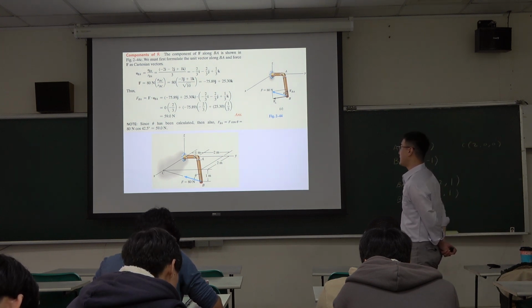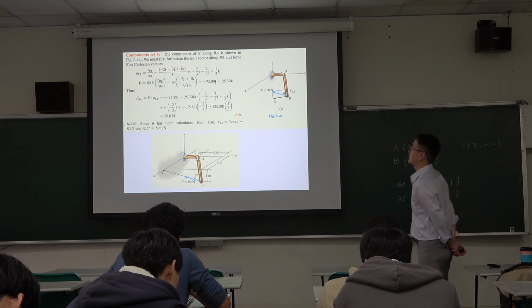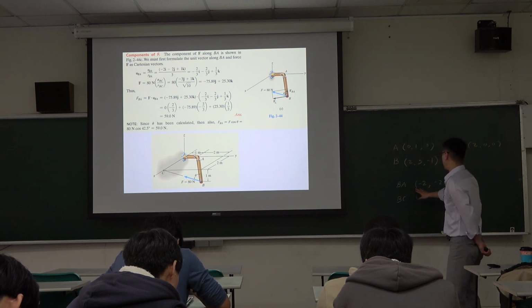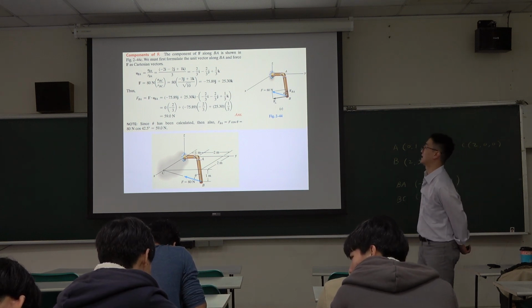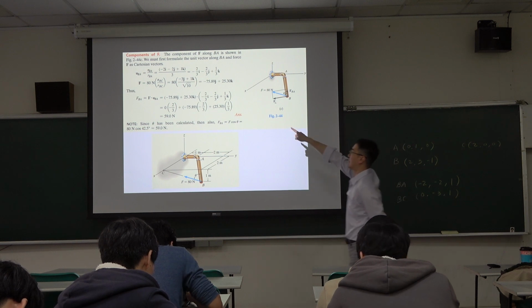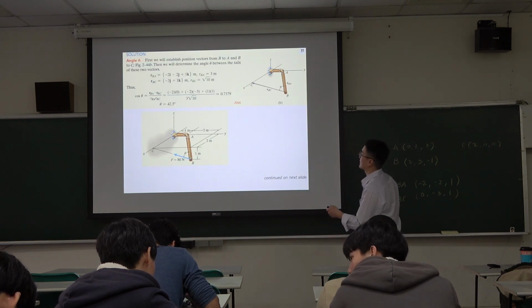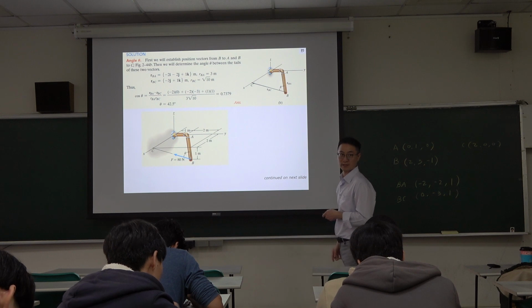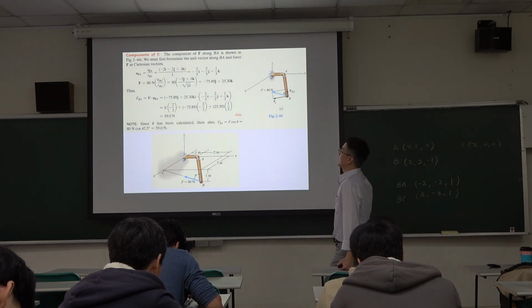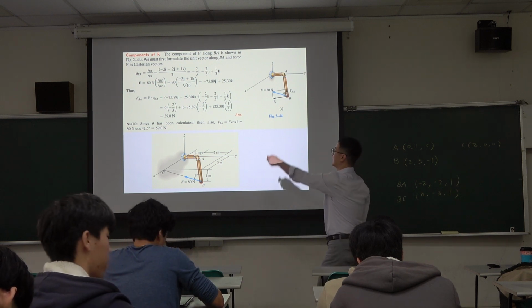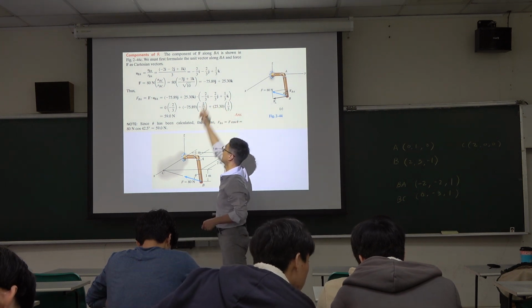And the unit vector for the position vector, the unit vector for BA direction, can be worked out from this part, because we know its scalar is 3. First line is the unit vector. So we use the force scalar times the unit vector to represent this force using a Cartesian vector. That's the top part here.